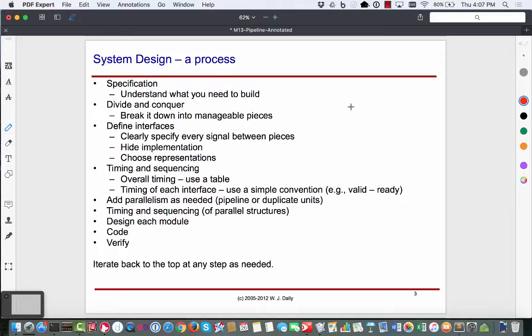How does this whole pipelining and parallelism fit into the design process that we indicated, that if you're using things like Verilog and EDA tools, one ends up following? Essentially, you start out with some sort of specification of what you want: this input, that output, and you might be given some timing requirements, like min and max delays between some action and the corresponding reaction that the system is producing. Then you figure out how your system is going to interact with the outside world. And then the other thing you do is come up with an algorithmic strategy.